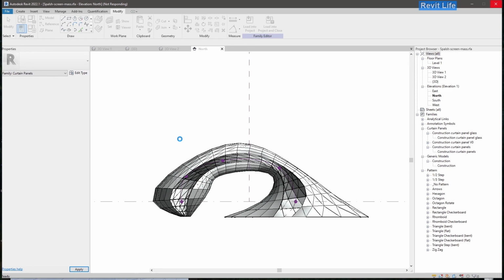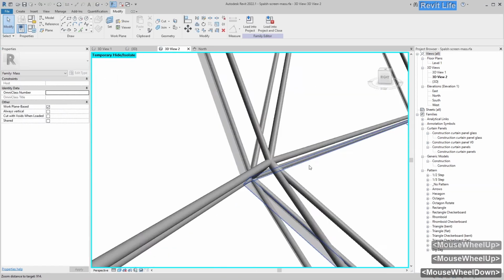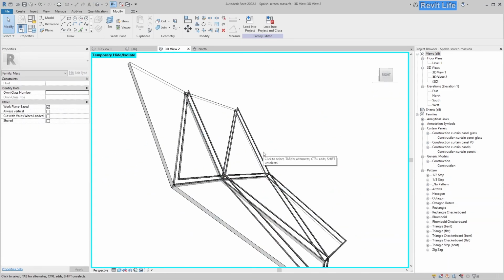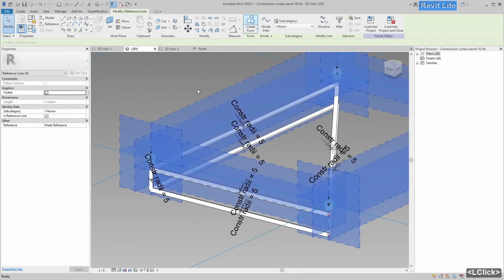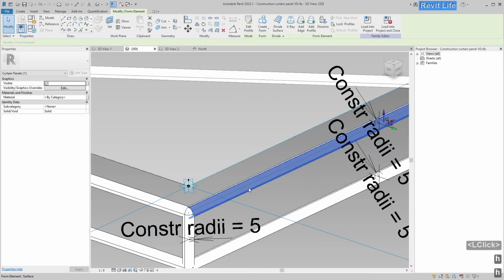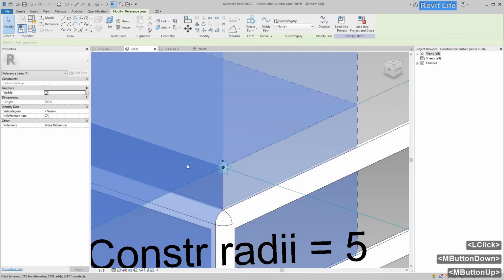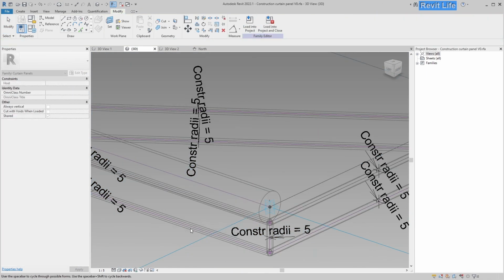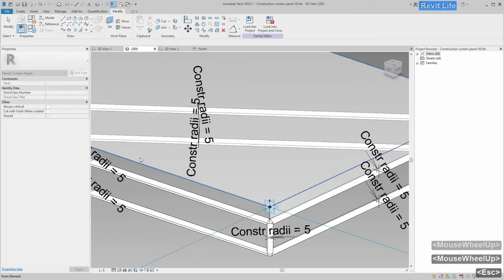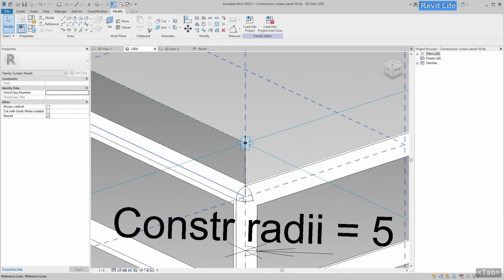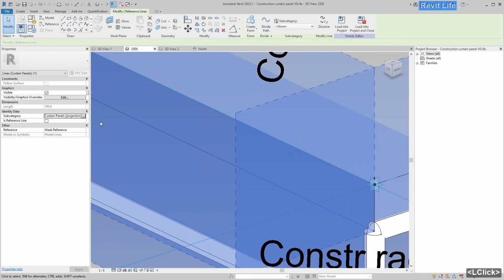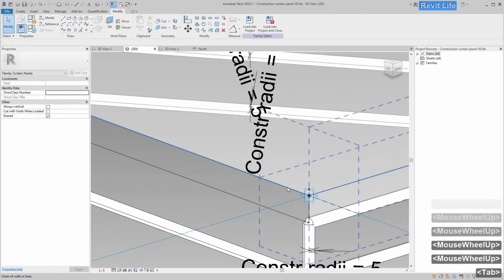And I don't know why, but when I use model lines, every pipe is extruded and every cell is populated. And I have no errors when populating the divided surface. So finally it works, but it gives me another layer of struggle because it's a bit difficult to create a parametric family using not reference lines but using model lines.